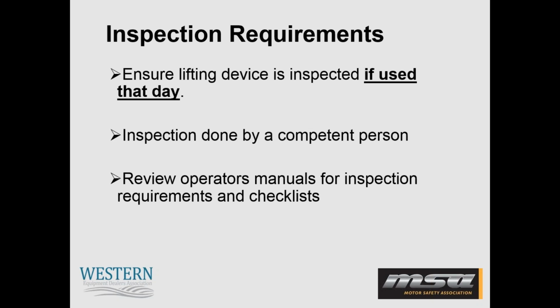And further to that is that you are only using jacks or lifting devices that have been tested, certified, and rated. This inspection for your lifting device needs to be done by a competent person, and that inspection needs to be documented and kept record of, that you've checked your lifting device.